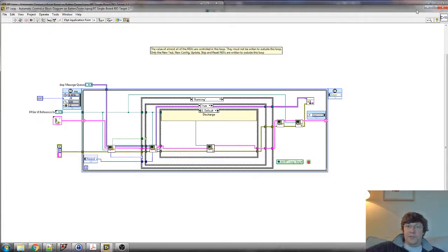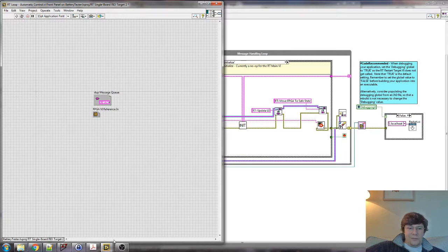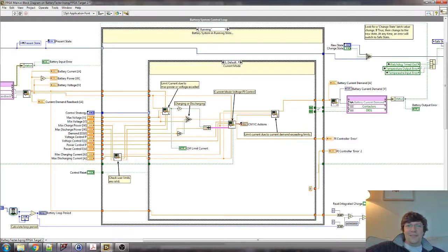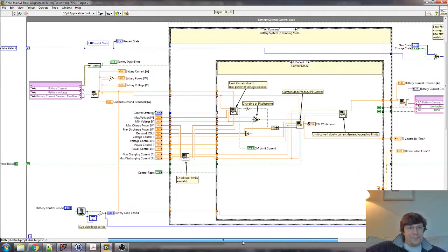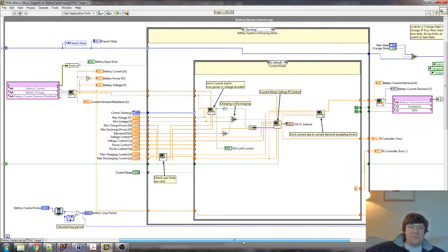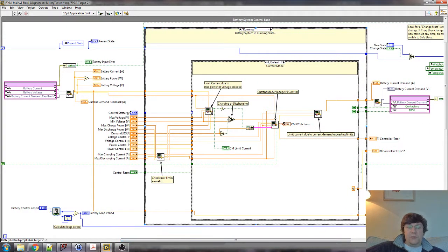So the meat of this then, if I can get back to it, nothing like a few windows to make you happy, is there? This is the control loop on the FPGA. We're taking the three reads, so we're not reading a lot of data really, it's only 3 channels and we don't have to read it particularly fast. A few kilosamples per second is more than adequate for most of the things we want, and if we want to do some burst recording where we have maybe 50 kilosamples per second to do some sort of 20 kHz Nyquist bandwidth for some noise setup or something like that.